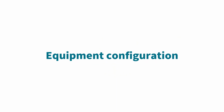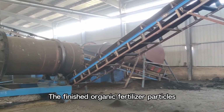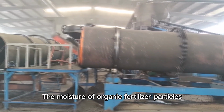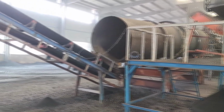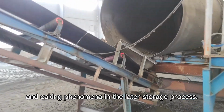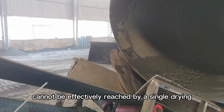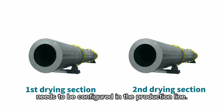The drying section. Equipment configuration. Drum type dryer. The finished organic fertilizer particles are sent to the dryer for drying treatment to reduce humidity. The moisture of organic fertilizer particles after granulation is about 40 to 45%, and the moisture needs to be reduced to less than 20% by drying equipment. If not, it will produce powder and caking phenomenon in the later storage process. If the storage humidity cannot be effectively reached by a single drying, a secondary drying system needs to be configured in the production line.